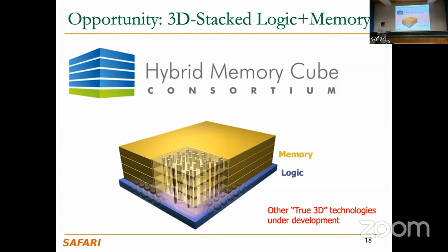I'm just clarifying this because, as you can imagine, we will be able to have different cores or different accelerators in different vaults, and they may eventually need to communicate in some way, right? And they will have local access to whatever is placed, the part of the DRAM layers that is placed on top of them, while they don't have direct access to other vaults, right? To the data residing in other vaults.